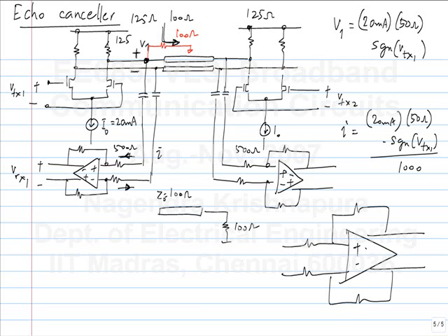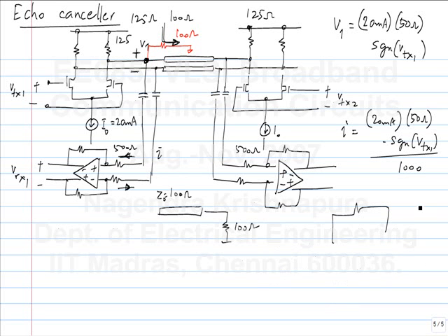So I have this. I can measure the impedance by connecting a 1 volt source here. If I do that, the current that flows is 1 volt by 1000, right? Is that okay? If I measure it differentially, each end will have an impedance of 500 ohms to ground. Now what is the output that it will create, VRX1? 1 volt, it's the same thing. This times 1000 is the differential output. Each of these is 500 and 500.